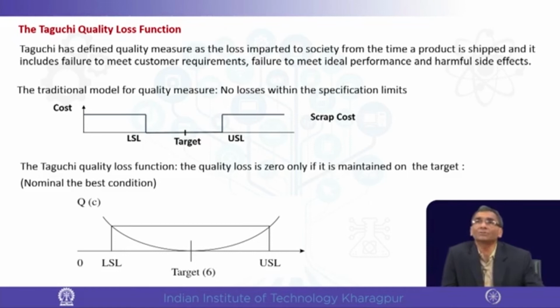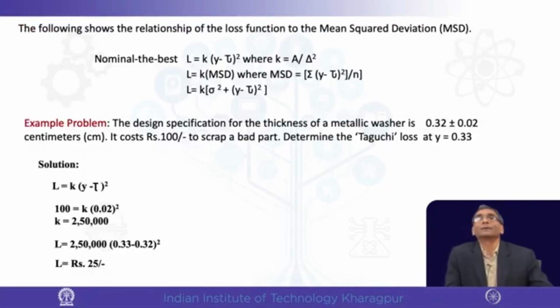So any deviation, though permissible according to the upper and lower control limits, matters, because this loss function is very important. It is a parabolic function proposed by Taguchi, and you can see that if we move from the target value to the left or right side, the USL or LSL side, the loss goes up. There is one short calculation that you will see. We will do the nominal-the-best kind, that is a nominal dimension with fluctuation.